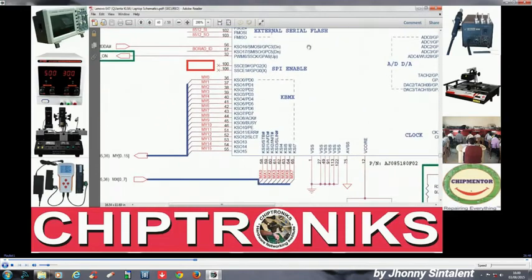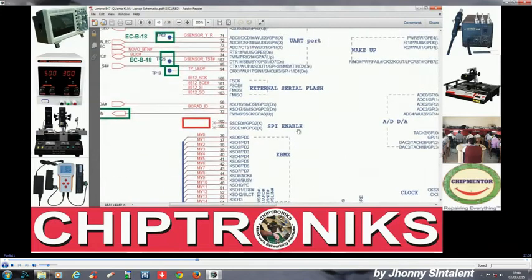And what is the keyboard controller? We have already seen 8042. The 8042 keyboard controller is present inside this chip, and the keyboard encoder is present inside the desktop keyboard. Whereas in a laptop keyboard, both the keyboard encoder and keyboard controller are present inside this chip.